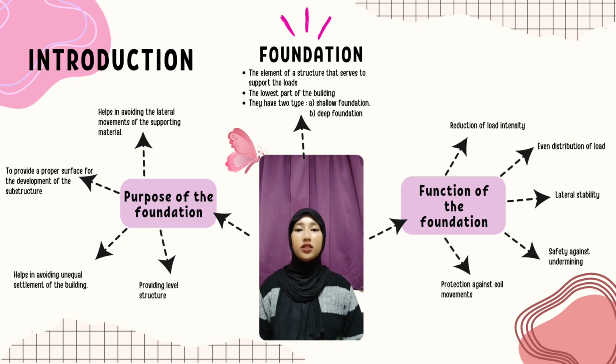Also, lateral stability: the foundation anchors the superstructure to the ground, thus imparting lateral stability to the superstructure. The stability of the building against sliding and overturning due to horizontal forces such as wind and earthquake is increased due to the foundation. After that, it provides safety to the structure against undermining or scouring due to burrowing animals